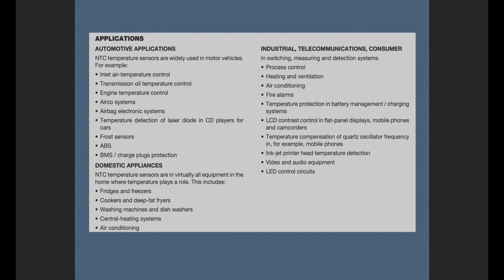An NTC thermistor is a semiconductor. When mixed with dopants, metal oxides like iron, chromium, magnesium, cobalt, and nickel become N-type semiconductors. The metal oxide mix is heated until it melts, then cooled and cut into small ceramic sheets. Raising the temperature of this material increases the number of charge carriers, promoting electron mobility and thus lowering the effective resistance. Thermistors come in different types: bead, probe, washer, screw, disc.